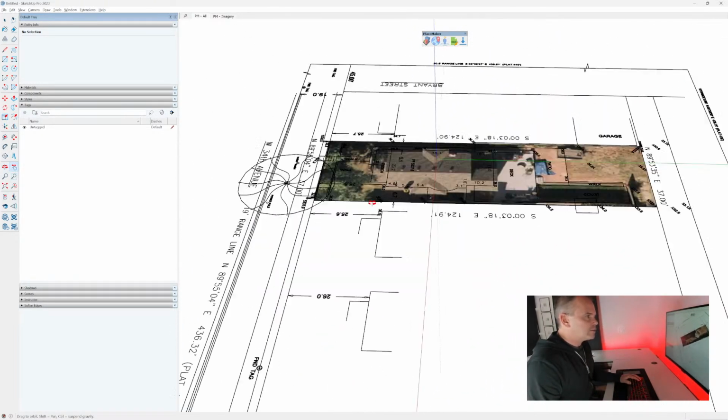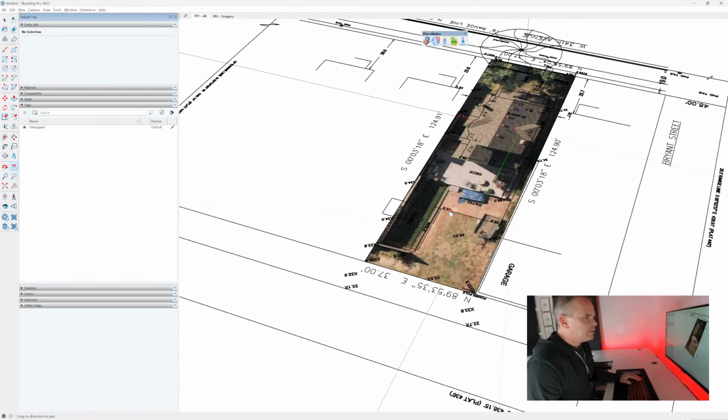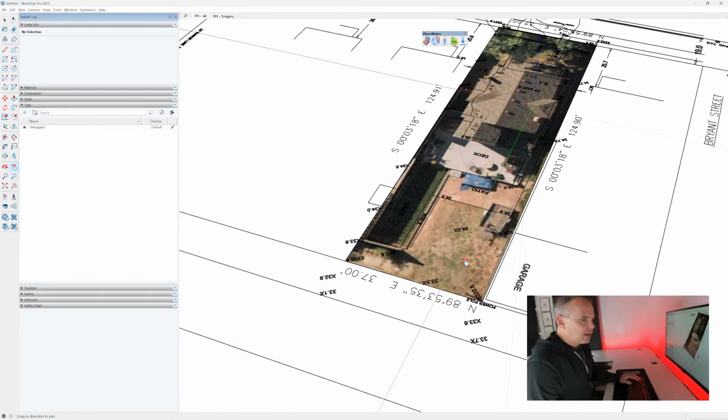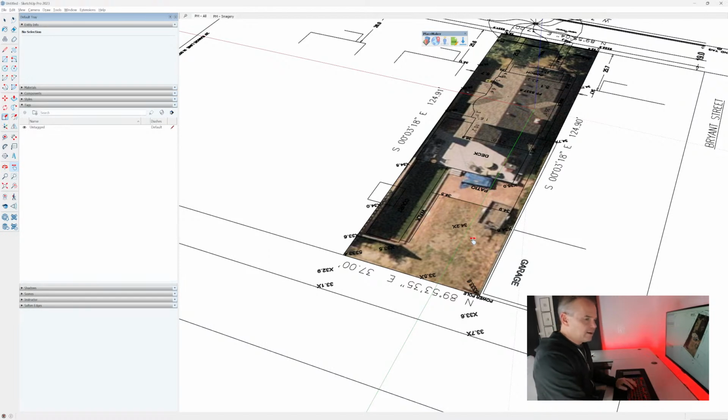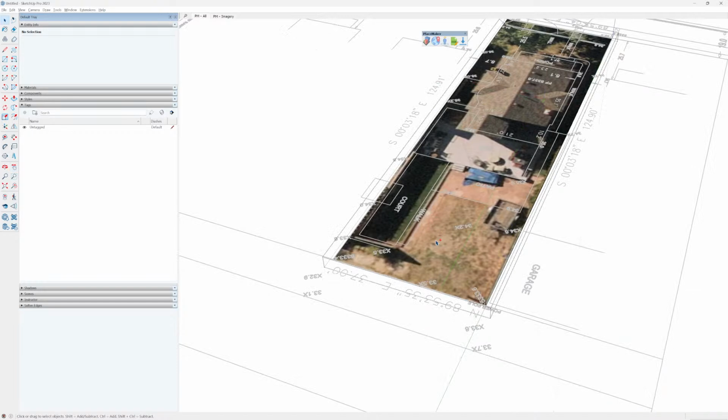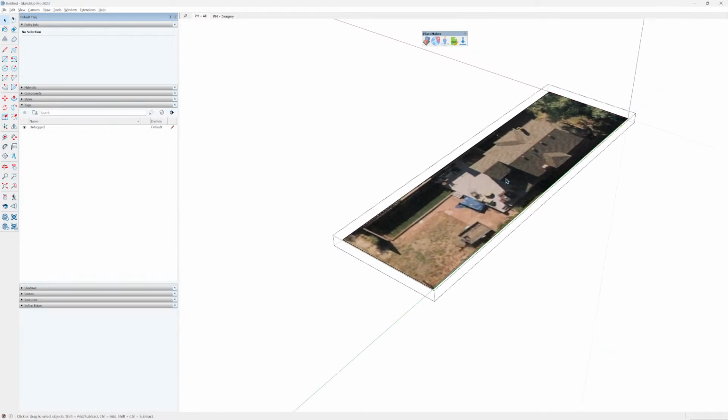All right, so first things first, we need to define, this is the alley back here. And we're going to need to define our rear 35% of the lot. Now, I can double click to select the surface as well as all the bounding edges. I can hold Control and Shift to remove these other pieces from my selection, leaving only the back edge and the front edge.